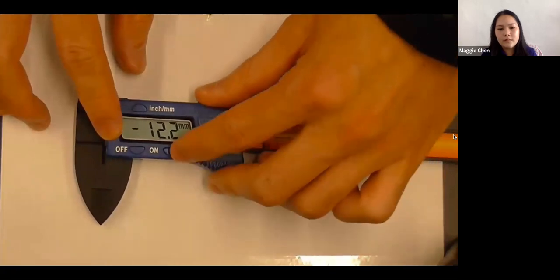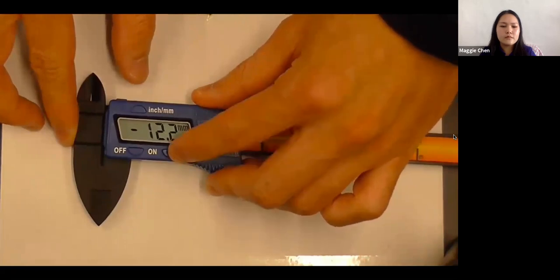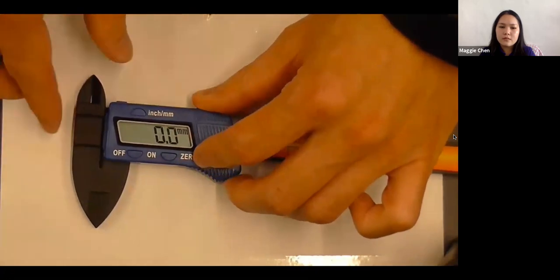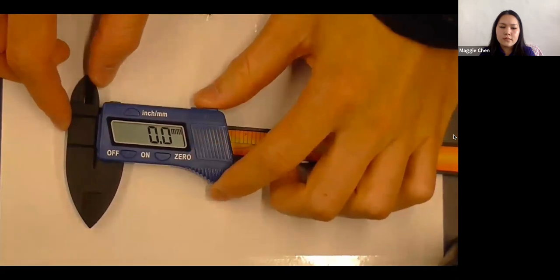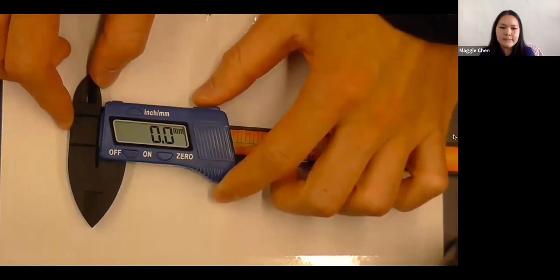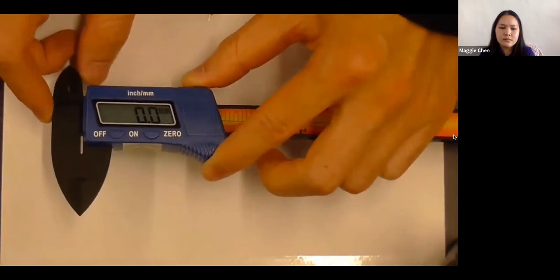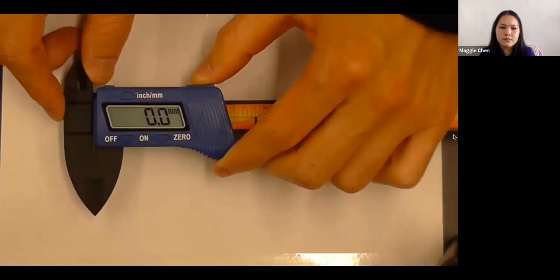So we can fix that by making sure, again, our caliper jaws are completely closed, and then pressing the 0 button, telling it that this is what 0 looks like. So that means what we have done is that we have calibrated the caliper to a known standard value, that value being 0. Now, these calipers are on the same page as us, and they are ready to go ahead and get measuring.